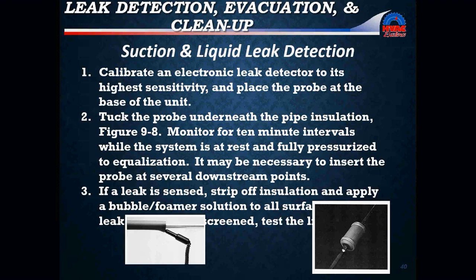Okay? Suction and liquid line filter dryers are common causes of leaks. Solder and braze joints are common causes of leaks. Liquid line sight glasses should also be checked.